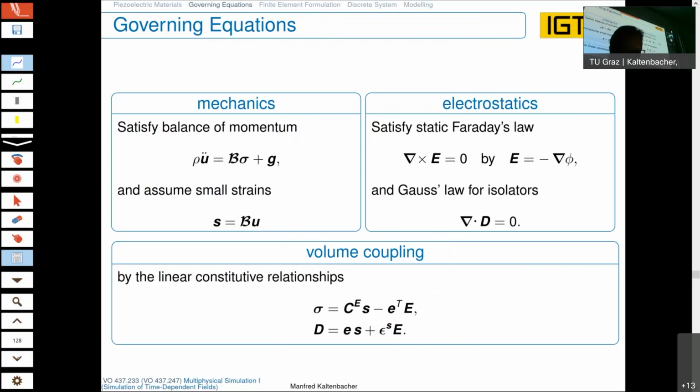Okay, so we see, or let's say, hopefully we have these entries given somewhere from a material database. Be very careful when you do simulations in practice. Mostly what you get from the manufacturers is not correct. So don't believe the values from the manufacturers. In this case, it would be good to have the possibility to measure these material parameter entries on your own.